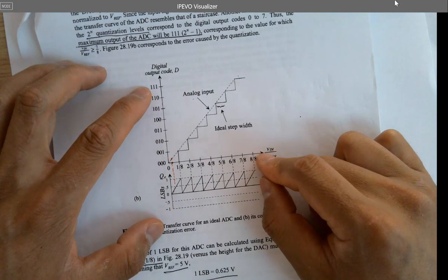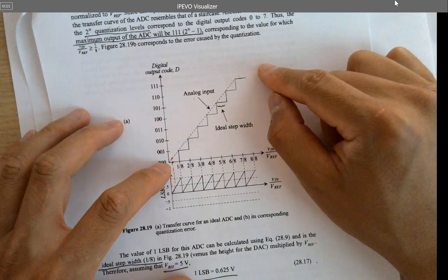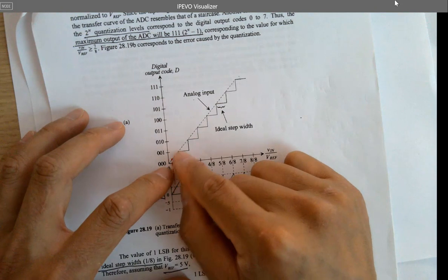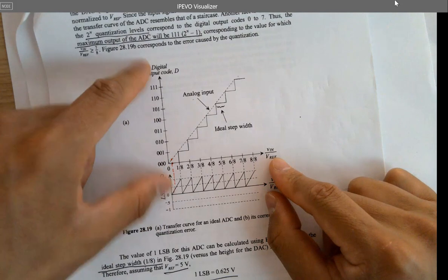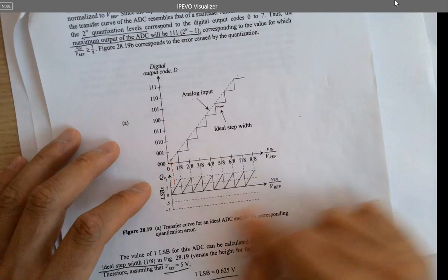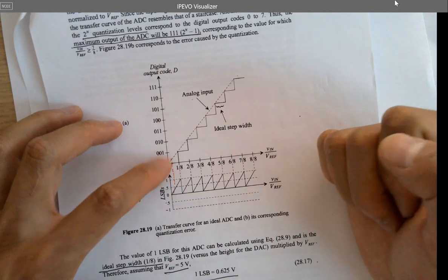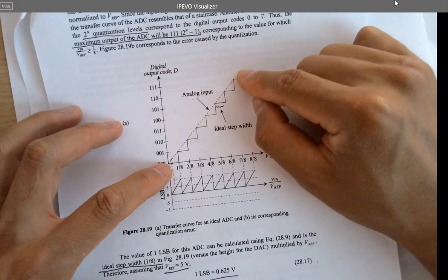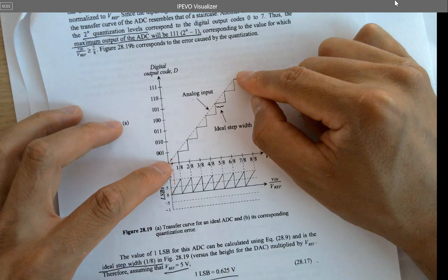Pretty poor resolution. That's why you are seeing huge steps. But you can smooth them out using a low-pass filter later on, but still not ideal because it's not able to resolve smaller changes. So the x-axis will be the analog input, and the y-axis will be the 3-bit digital output. And the quantization error here plots the difference between the converted value and the ideal value. The ideal curve is the dashed line, the linear line in the middle, right?